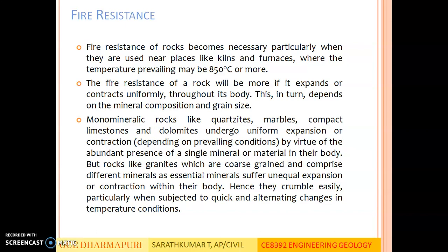only one mineral. But rocks like granites, which are coarse-grained and comprise different minerals as essential minerals, suffer unequal expansion or contraction within their body. Hence they crumble easily, particularly when subjected to quick and alternating changes in temperature conditions.